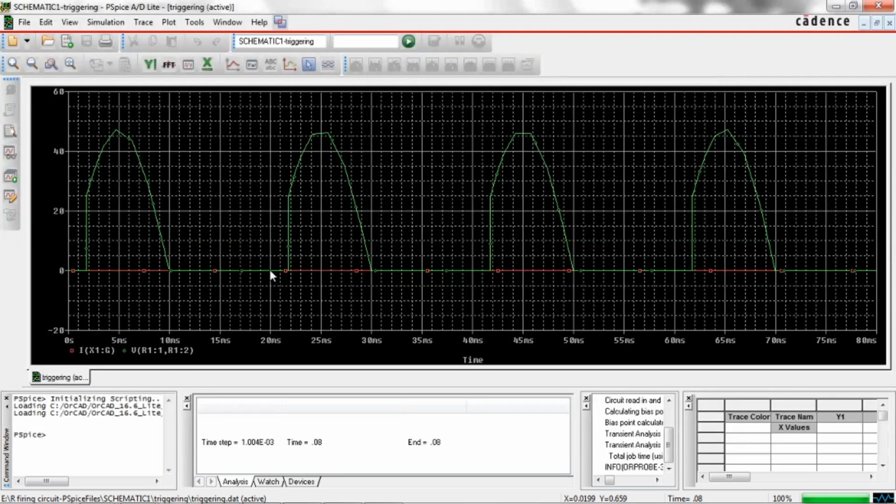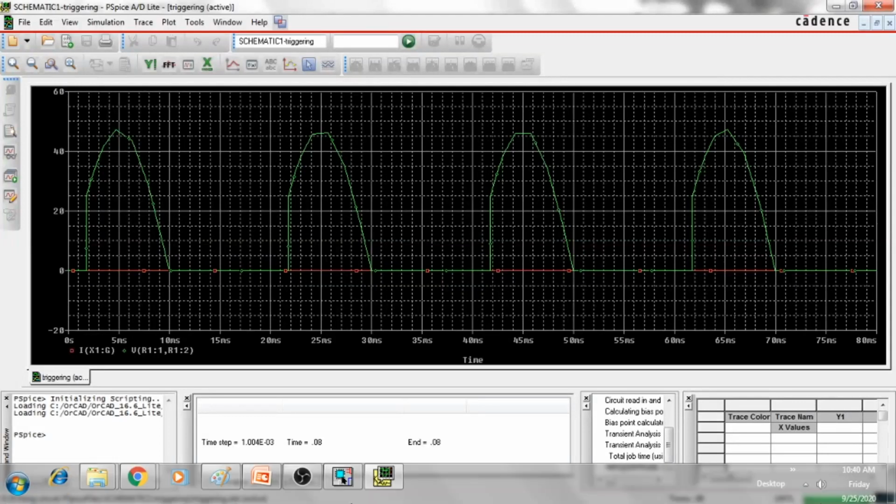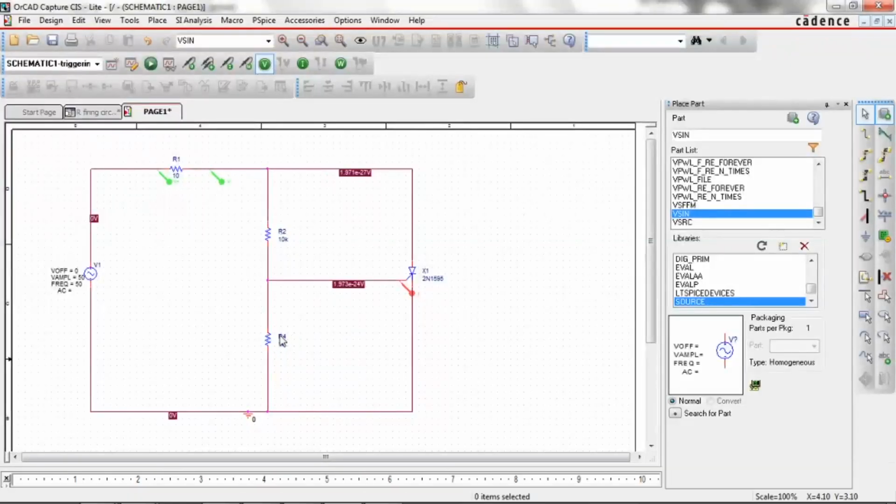Because the input voltage becomes negative half cycle. It is a negative half cycle, so in the negative half cycle J1 and J3 are reverse biased. Again, in the next half cycle, why is it not receiving any current, and why is voltage not existing across the load? Because whatever voltage is developed across this resistance R4 is not enough to give the gate current, that minimum is 1.9 milliamps.